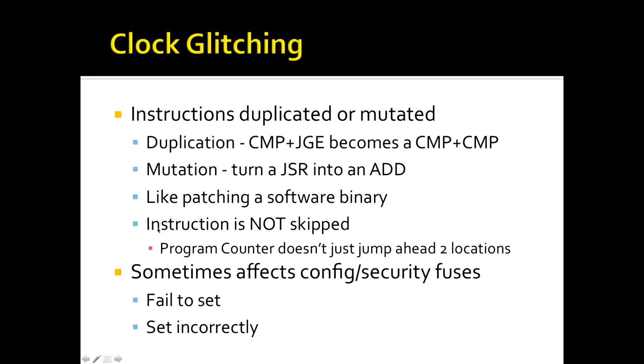So sometimes this quick burst of clock frequency can affect your config or security fuses. So they'll either fail to set in some cases, or they're set incorrectly. So this could actually be kind of helpful to wipe out certain code protect fuses or things like that. But it's a lot more particular in how it works depending on the device.